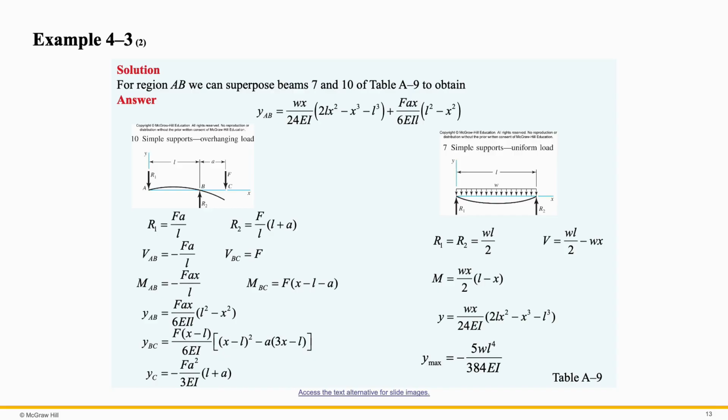You can also refer to table A9. Table A9 provides the deflection equations for different kinds of load configurations. You can refer to table A9, find the deflection equations separately for these corresponding load configurations, and then combine them together.